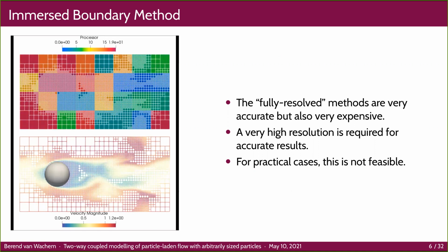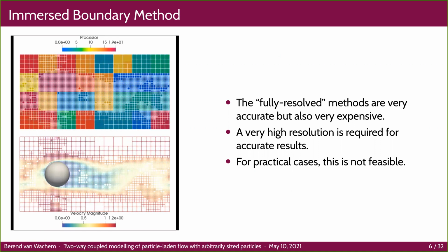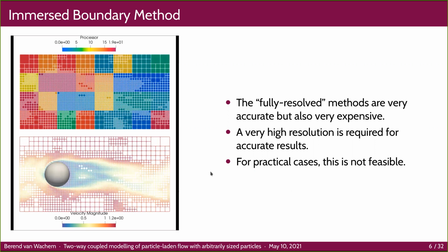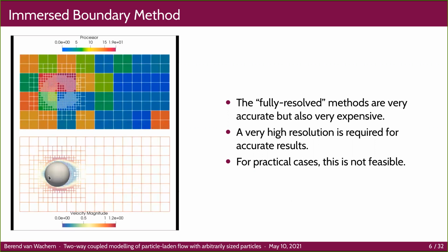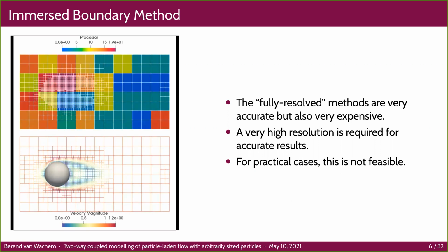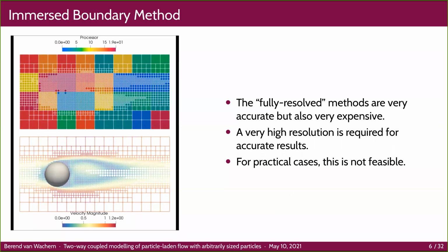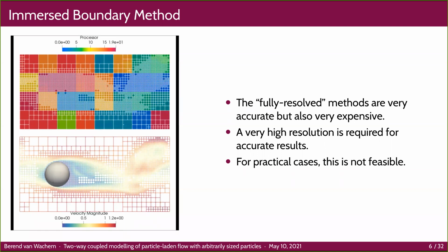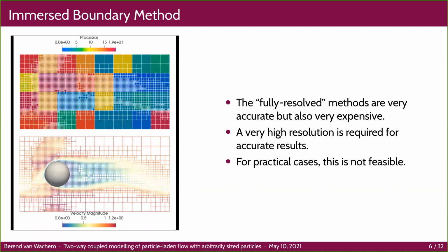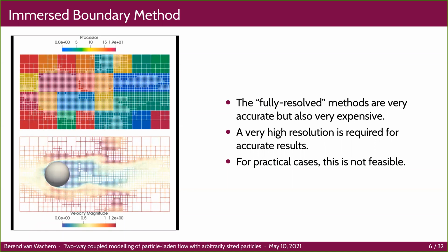So in practice, what you need is an adaptive mesh, as you can see here on the left, which we're actually currently developing. Where you have a particle in flow, you resolve the mesh adaptively as the flow develops. That means you save mesh cells in areas which are not very complicated to model, but you can include mesh cells where they are needed, namely at the particle where you are enforcing the sources for the no-slip condition, as well as away from the particle where you have very complicated flow features or features of the domain.